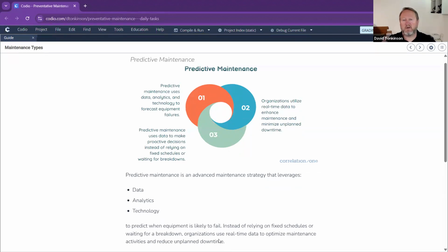Okay, at which point you can look at unit 12 and go, what's wrong with unit 12? So let's have predictive maintenance on it. Could it be the air filter has become clogged there? Could it be one of the hoses is jammed in it? Could it be a bird has decided to nest on the cooling system for that particular item? Okay, so that is predictive.